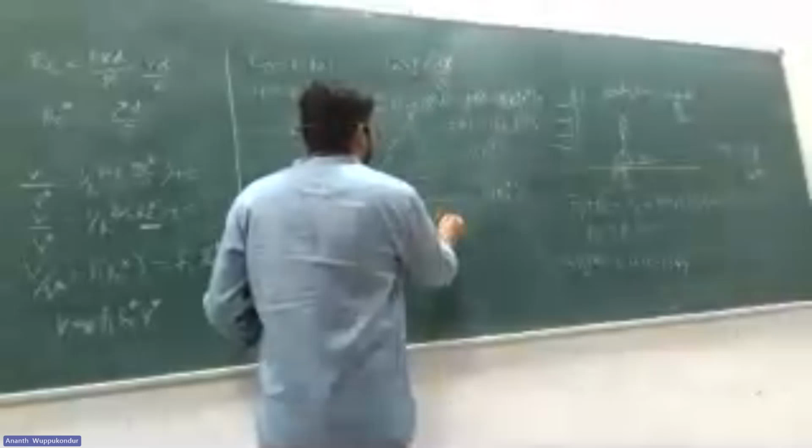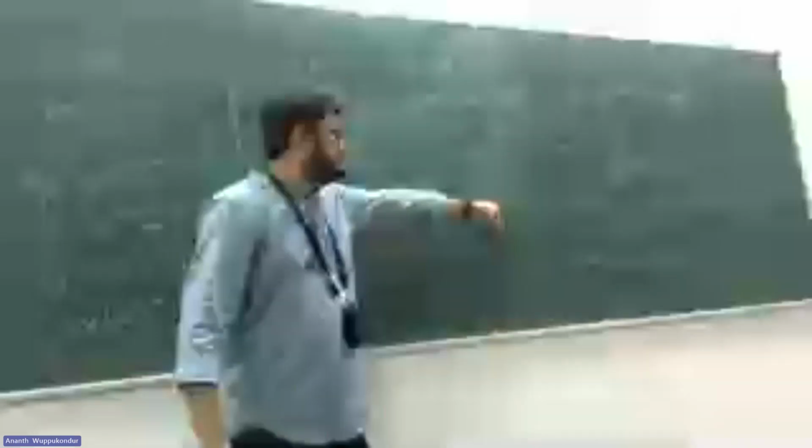So this is what you would get. So on the right hand side, you would have some function of RE star. So all the constants K1, F1, F2, K2, all of them you can take to the right hand side. So you have some function of RE star. And on the left hand side, in the numerator, we have rho multiplied by V star square. And in the denominator, we have gamma W S minus 1 divided by D.